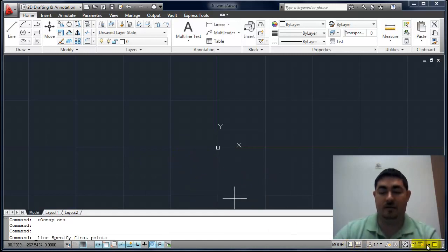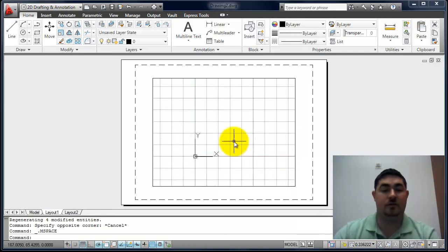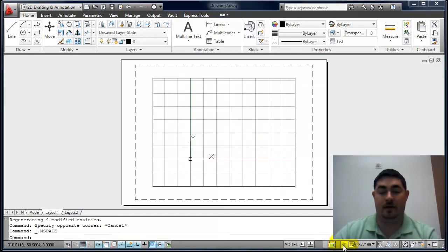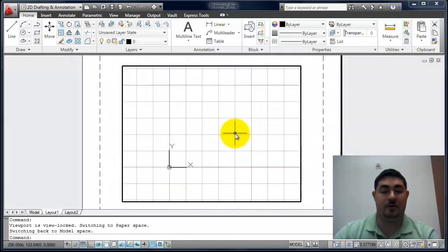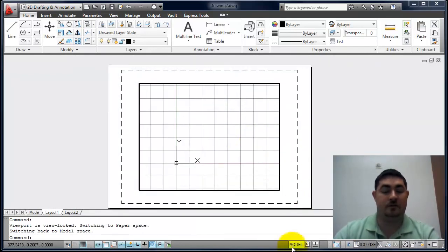Over here on the right, there are some other options that have to do with your layouts and some annotation things. So if I go to the layout, I go into the viewport. Now I've got a couple. One right here is the viewport scale. The one next to it is a lock button. Let me lock the viewport at that scale. So if I have it unlocked, it zooms inside the viewport. If I lock it, now it zooms the whole viewport and layout together. This model button right here is just a switch between model and paper, but I can double click to do the same thing.